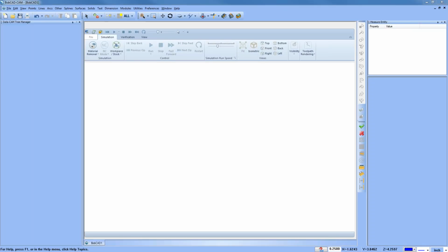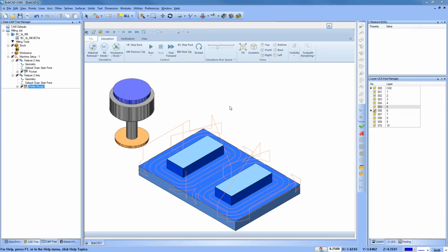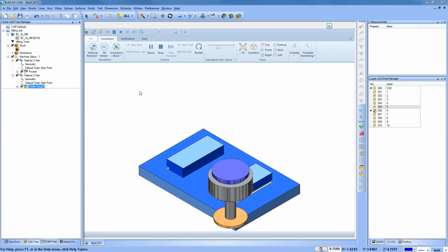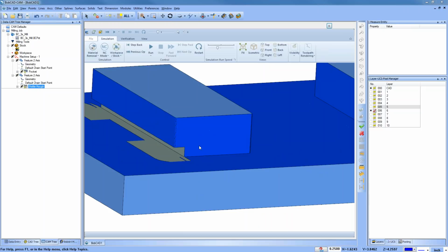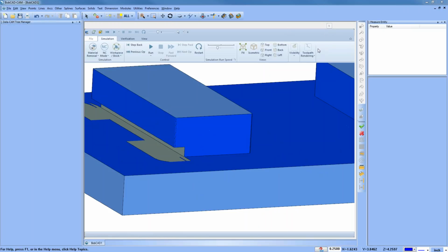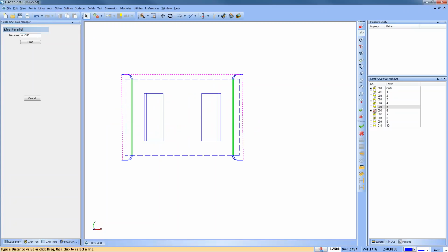A lot of times you might have a woodruff type cutter. There may be a radius on that edge, and we're coming in here and we want to add a relief. So here you can see we have this relief to come in down at the bottom. If we need it to be greater, it could be greater, so we'll do like a parallel. We'll make it a little bit further in here.